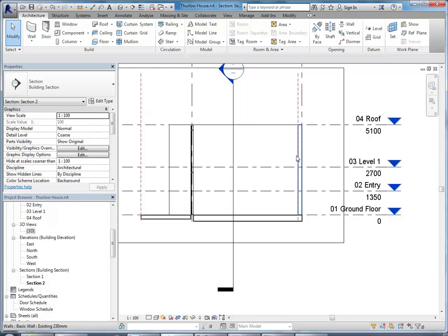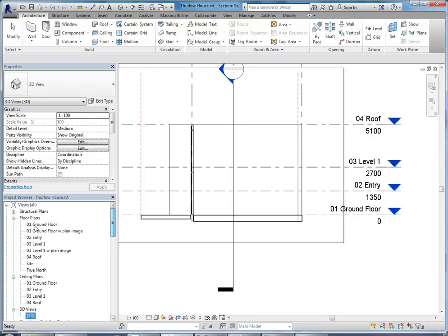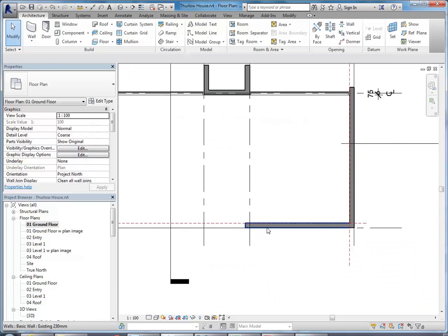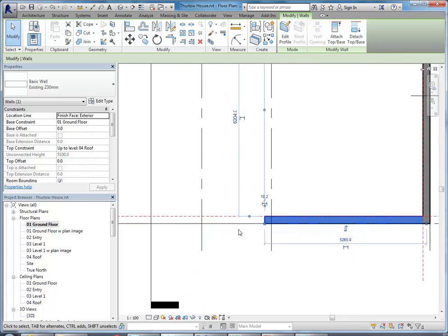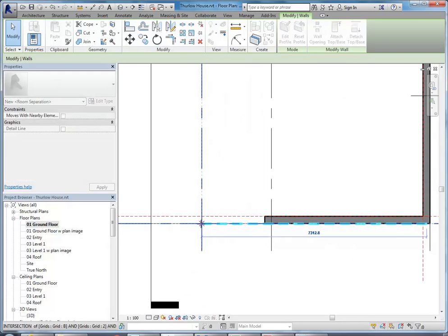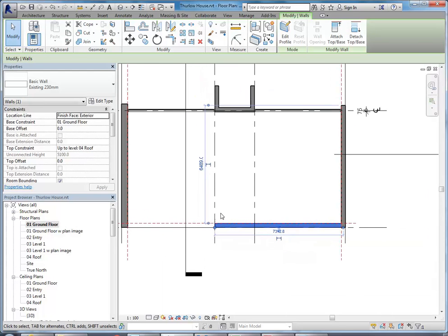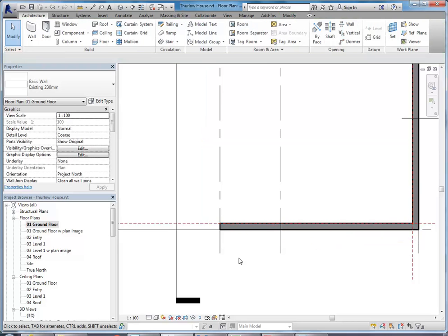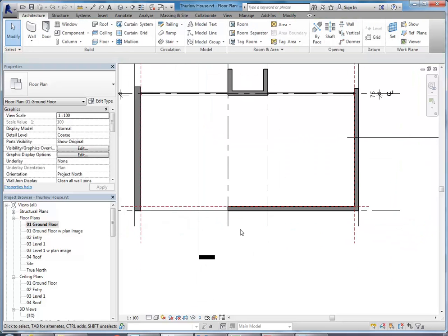Okay, so then maybe in the floor plan, I'm going to select that wall and simply drag it across to the grids. So hopefully you can see how useful those grids are going to be, even before we do the stairs. Yeah. Yep. And that's on the outside of the one at the bottom, not that one. The one down the bottom. Oh, you've got to bring the grid down, I think. So it's the wall at the bottom, yeah, and then just dragging it across.